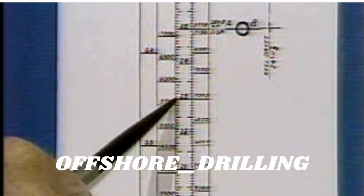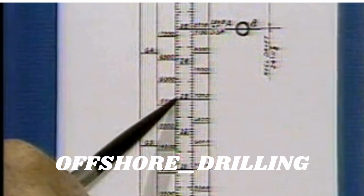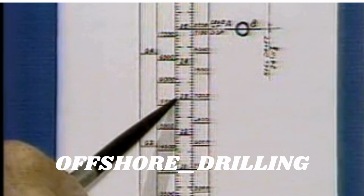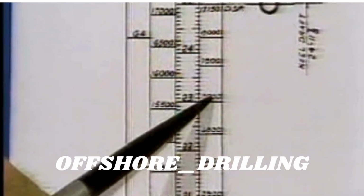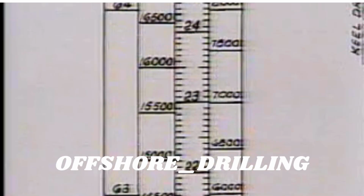To the left of this mark, we see the deadweight column, and the deadweight amount corresponding to a 23-foot draft is 7,050 tons. What this really means is that there is slightly more than 7,000 tons, these are short tons, of fuel, water, stores, drill pipe, and so on board.